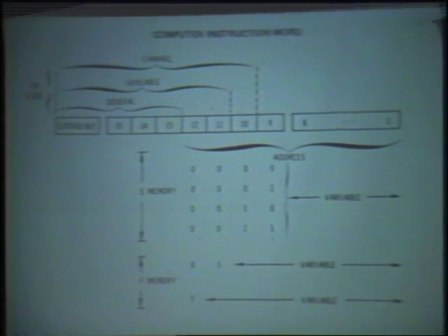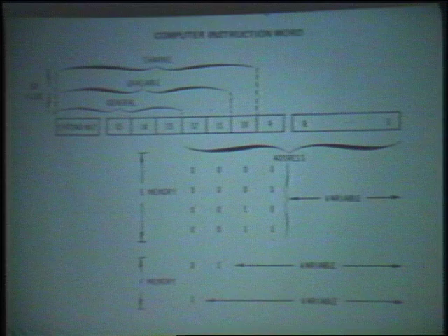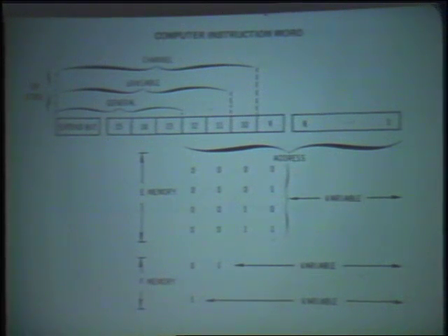There was an extend bit provided, shown over there on the left. And then there was multiple use of the bits through the center here. As you see, the opcode used these bits, as well as the addresses for various parts. The memory address field was extended by organizing the memory in banks, and a memory bank register provided 3 extra bits to address the 2,000 words of erasable memory, and 5 extra bits to address the 36,000 words of fixed memory, which would in fact be tacked on over in here on these addresses.